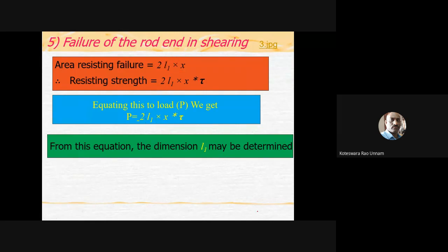Okay, you note it down. Those are a total of six steps of calculation. So first you have to calculate X. Then once you get X, you can calculate B1. B1 is nothing but your X. Then the thickness of the cotter is taken as X by 4 or B1 by 4. Both are the same only. Then the height and length of the jib head. If you want to take the jib head, that we will take as T only. So that is already calculated. So that is the first step.